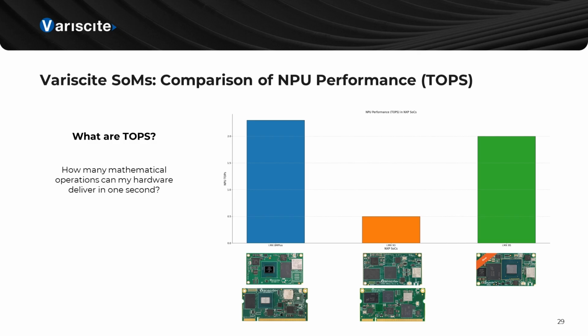Additionally, the i.MX95 incorporates specialized hardware blocks that accelerate common AI operations and a more efficient pipeline architecture that processes multiple operations simultaneously. Thanks to these improvements in algorithmic optimization, data movement, and processing techniques, the i.MX95 outperforms the 8M-PLUS despite having fewer TOPS. So while its TOPS rating is slightly lower, the MX95 is actually a much faster and more powerful AI processor, better suited for modern AI applications.